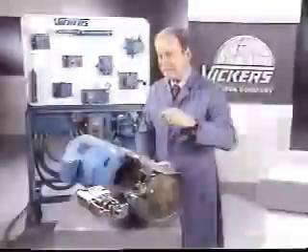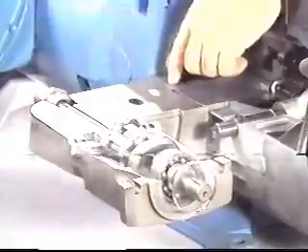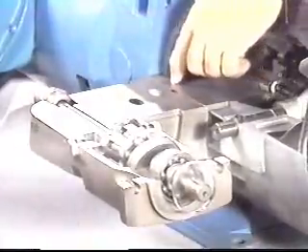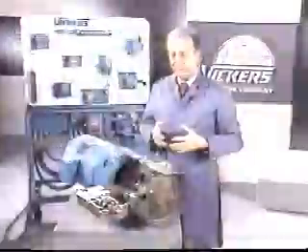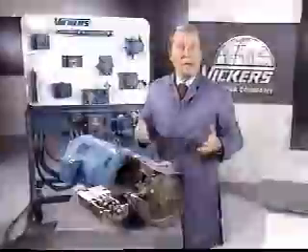Flow paths interconnecting the various components are cast or drilled into this section, combining everything we've discussed into one integral unit. If our application happened to be in a remote or hazardous area, a hydraulic motor could be removed and mounted separately, with lines running back to an adapter plate at this point. In this way, the pump, electric motor, and other components could be located out of harm's way. Now, let's move from our cutaway to a working unit.